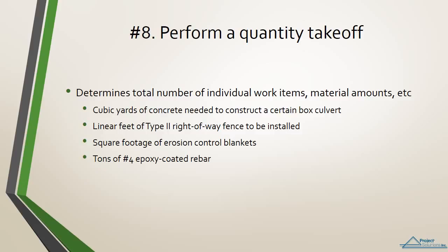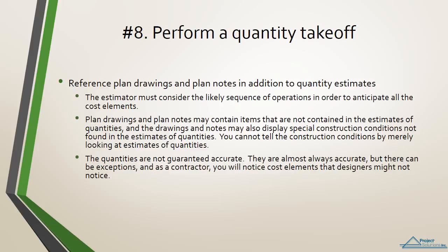Luckily for North Dakota highway contractors, the North Dakota Department of Transportation goes to great lengths to produce various tables that contain estimates of construction quantities, which they place in plan sets. Most of these estimates of quantities come from the plan and profile sheets in construction drawings. A note of caution though, when performing a quantity takeoff, do not merely reference the estimates of quantities. A careful estimator will also make a detailed reference of the plan drawings and plan notes.